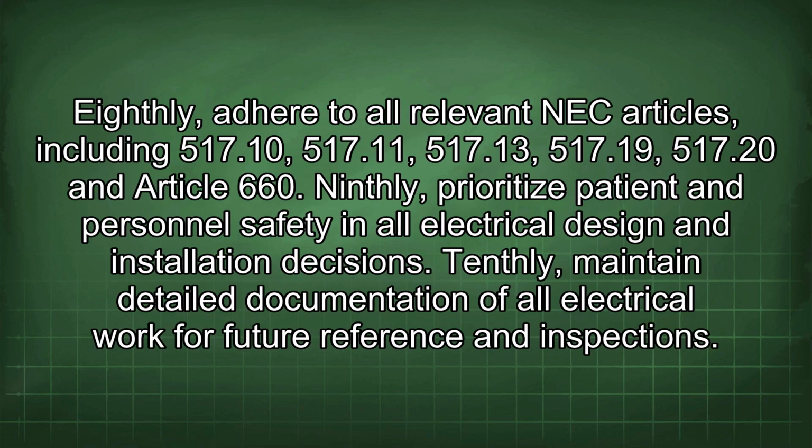Eighthly, adhere to all relevant NEC articles, including 517.10, 517.11, 517.13, 517.19, 517.20, and Article 660. Ninthly, prioritize patient and personnel safety in all electrical design and installation decisions. Tenthly, maintain detailed documentation of all electrical work for future reference and inspections.